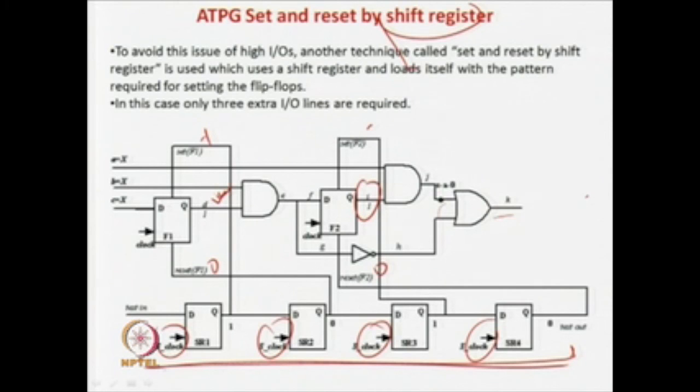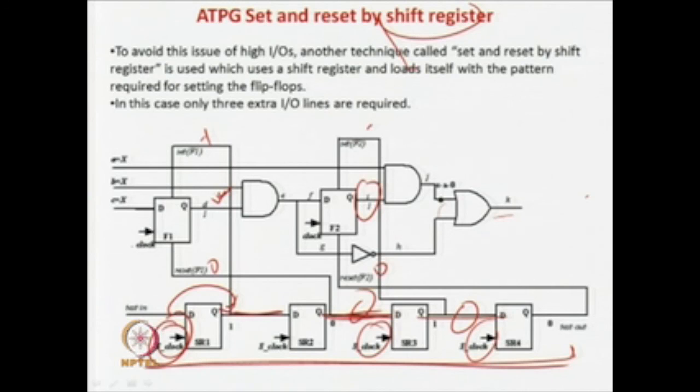But if you use the shift register, this output is connected to the input and so forth. There are no gates here, no gates here and no gate here. Directly you can feed it, so there is no delay. Once you apply the clock, the result data comes here, and immediately the data gets transferred to the input of the flip flop. Had there been a lot of combinational cloud over here, you would have to wait for the data to come from here to here, and only then could you apply another clock pulse. But that is not the case here. The output is directly connected from this to this. So your problem is solved. You can apply a very fast clock over here compared to the other clock, so that this filling up can be done at a very fast rate.